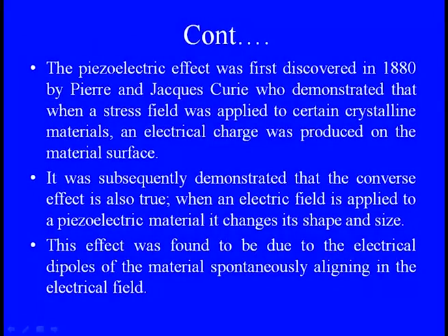It was subsequently demonstrated that the converse effect is also true: when an electric field is applied to these crystalline materials, there is a change in shape or size, which is why we call them piezoelectric materials. This effect was found to be due to the electrical dipoles of the material spontaneously aligning in the electric field, and because of this alignment there is a clear change in shape and size according to the intensity of the field or the dipole moment.